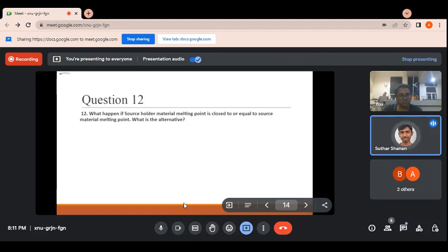But regarding SU8, the procedure differs, right? First we do soft bake and then hard bake. After that you expose to UV, right? Then we go for the development, then go for the baking process, like greater than 125 degrees centigrade.